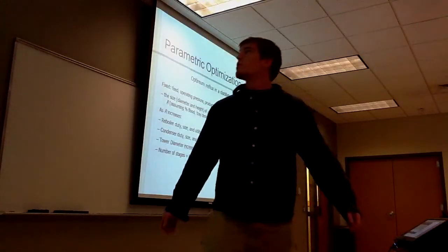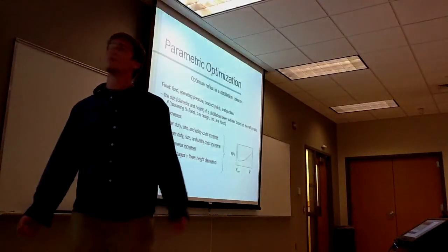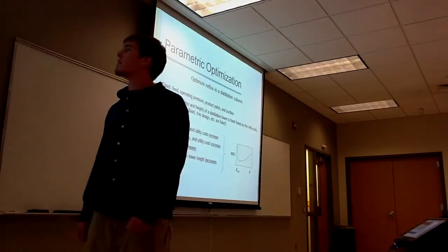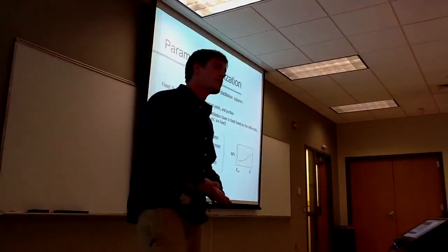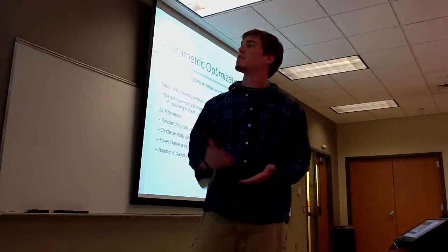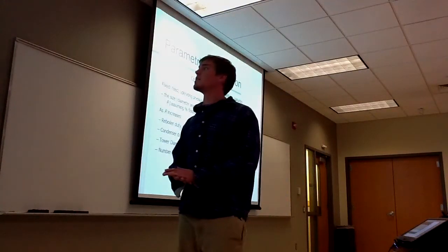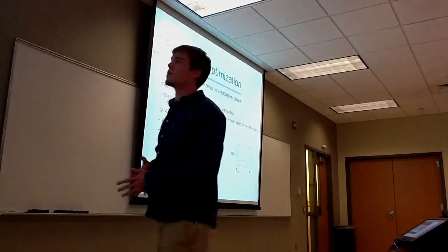But here's an example of finding the optimum reflux in a distillation column. It is a one variable operating function. Some of the things that are fixed in this problem are feed, operating pressure, product yields, and impurities. From there, the size of the distillation tower is fixed based on the reflux ratio, so the reflux ratio is your one variable.